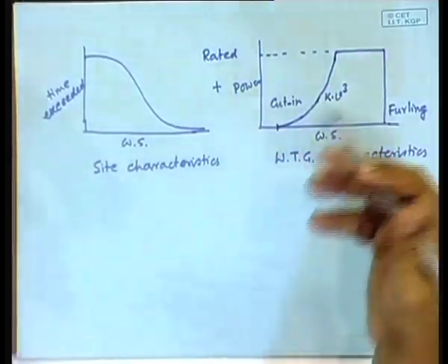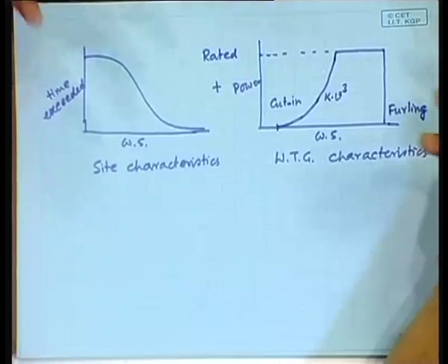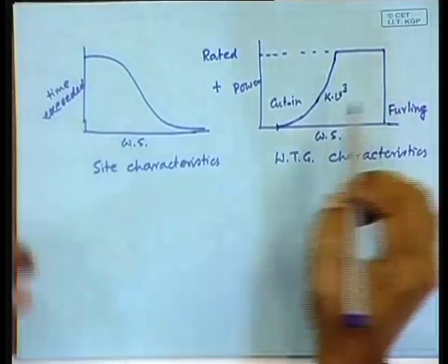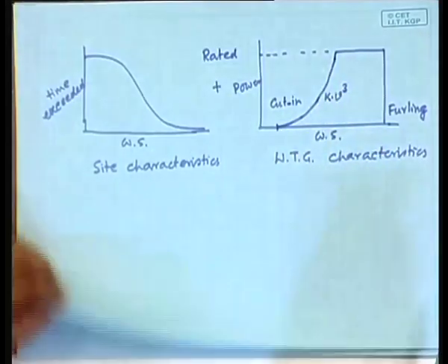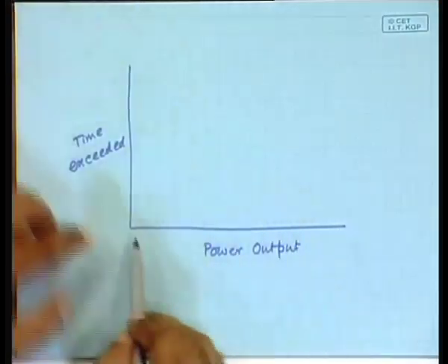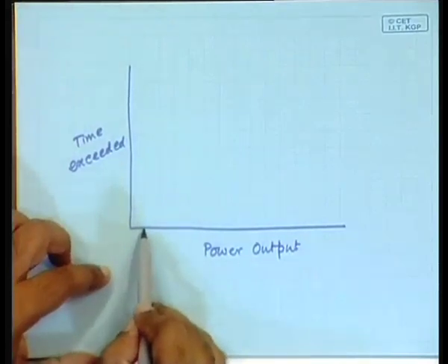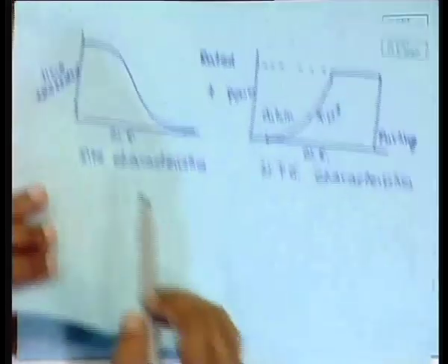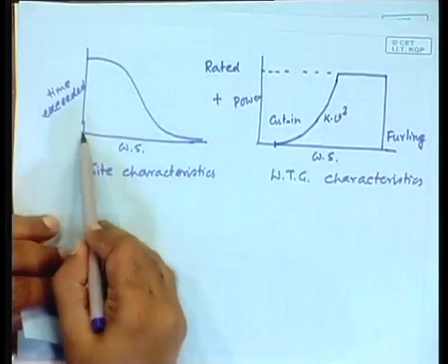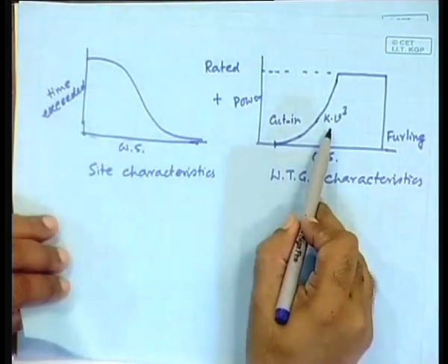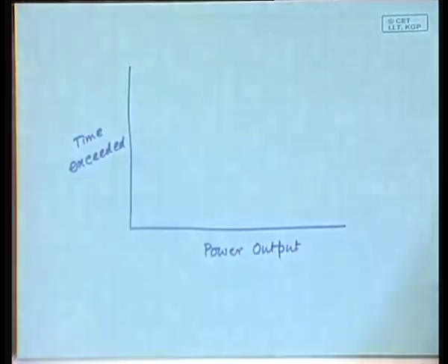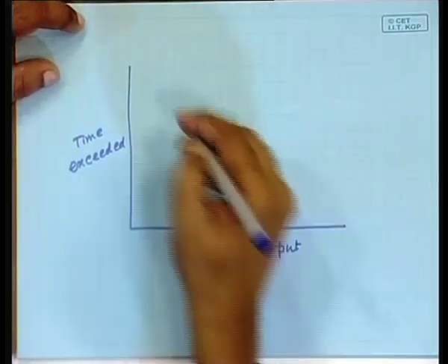The k is essentially half rho a Cp and all that. Whatever it is, there is a constant times v cube. So, these characteristics, if you want to put that here, what will you do? For every value of wind speed, the power output would be k times v cube, right. So, you draw a characteristic similar to this, but here the wind speed in this axis will be replaced by k times v cube, which will lead to a curve which is similar to this curve.